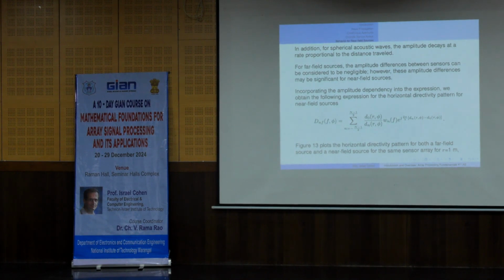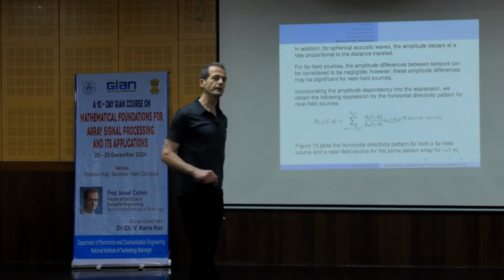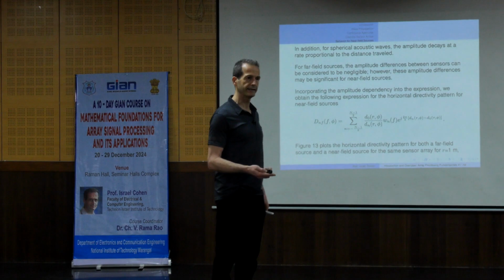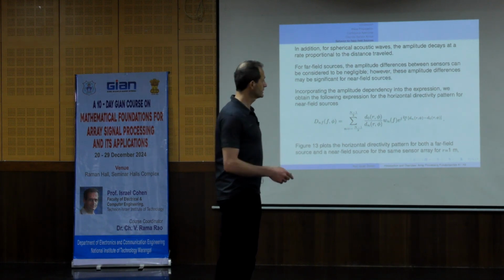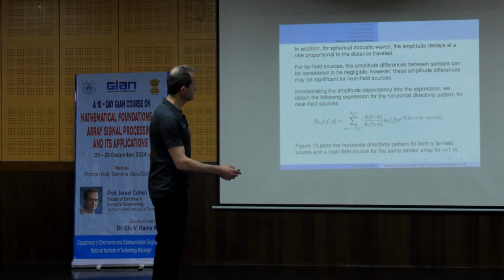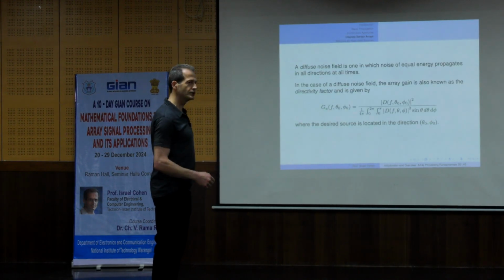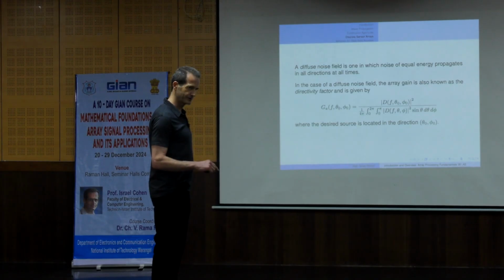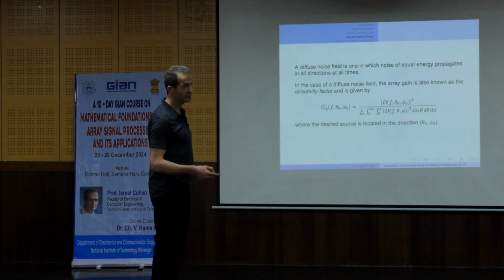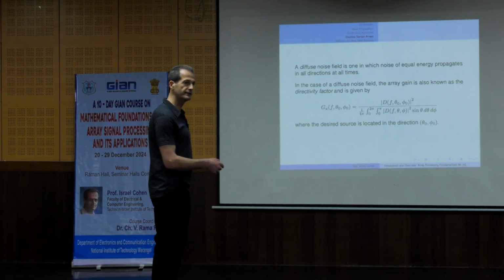Any other questions? Yes. Okay, white noise gain. So if we take the white noise gain, what does it mean? It's a good question. Actually, we will talk about it. You see, how do we change the array gain for white noise? We don't use this denominator. It will be different because actually, we don't take noise that comes from all other directions. So we will see how to modify this.